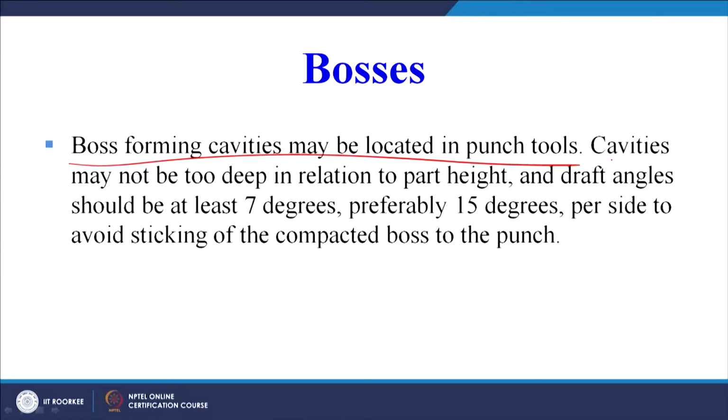Cavities may not be too deep in relation to the part height, and draft angle should be at least 7 degrees, preferably 15 degrees per side, to avoid sticking of the compacted boss to the punch.